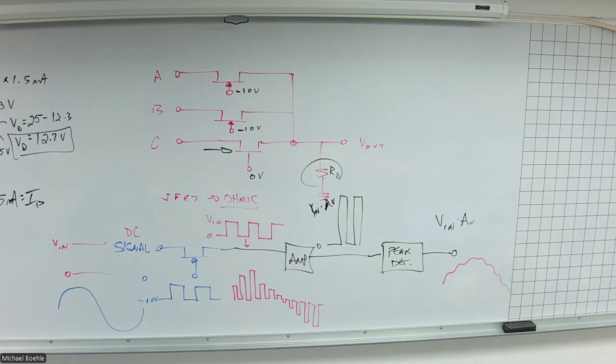One of the things about bipolar junction transistors is because we have a forward biased PN junction, when holes and electrons recombine, which is what's happening when they're forward biased, that actually creates some amount of noise. A JFET amplifier has no forward bias junction, right? The gate is actually reverse biased. So you don't have that recombination noise happening in a JFET. So very useful for me there.